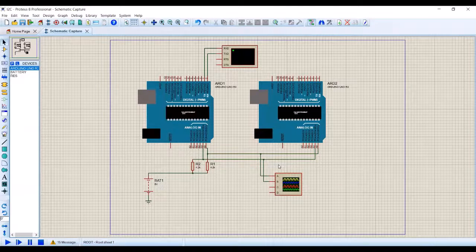And if the slave does not acknowledge, you can also see from these data lines, and then you know where the problem happens, and it is easy to use to troubleshoot. So this is how you troubleshoot. That is some kind of extra knowledge that I have given to you.